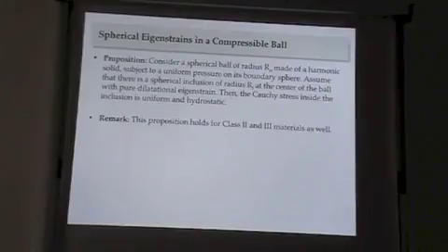And then you have this proposition that you have a harmonic material, and you're respecting the spherical symmetry, pure dilatational eigenstrain in a ball, then Cauchy stress is uniform and hyperstatic. And so this, we showed it for class 1 materials, for the other 2 it holds as well.